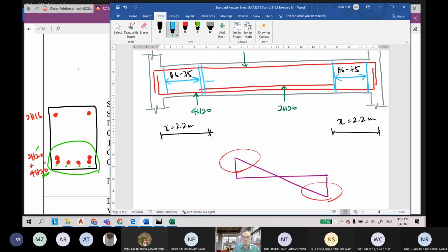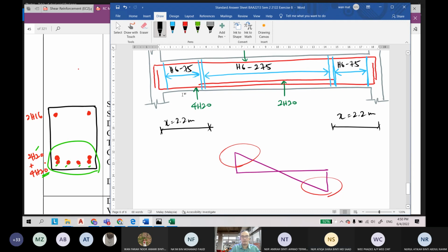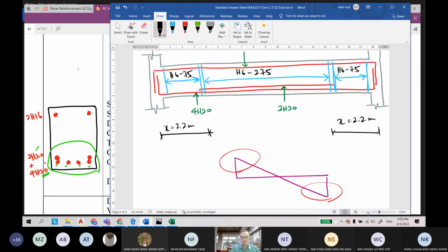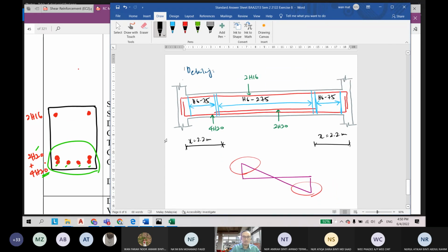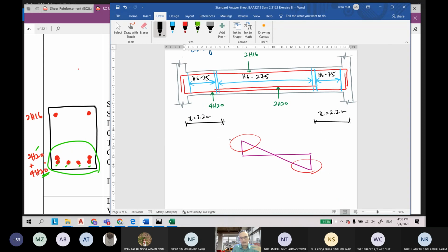Okay, what is our reinforcement? Can somebody tell me? This is how to do the detailing. H6. Check back at the mid span. 275. Okay, good, 275. So, reflecting back on our knowledge of structural analysis, since near the support the shear is maximum, it is very high here.